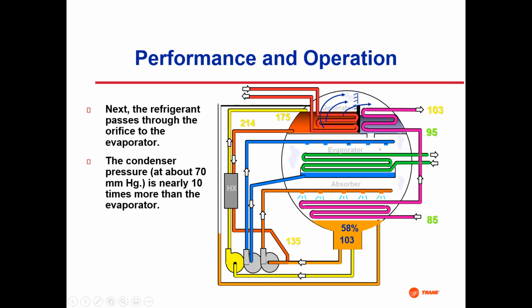And then the liquid flows over the evaporator tubes to keep them soaked with liquid water, so the water will continue to evaporate and provide the cooling effect. And then we've got a little tray down here that catches any water that didn't get vaporized, runs down through a pump, and then we pump it up.